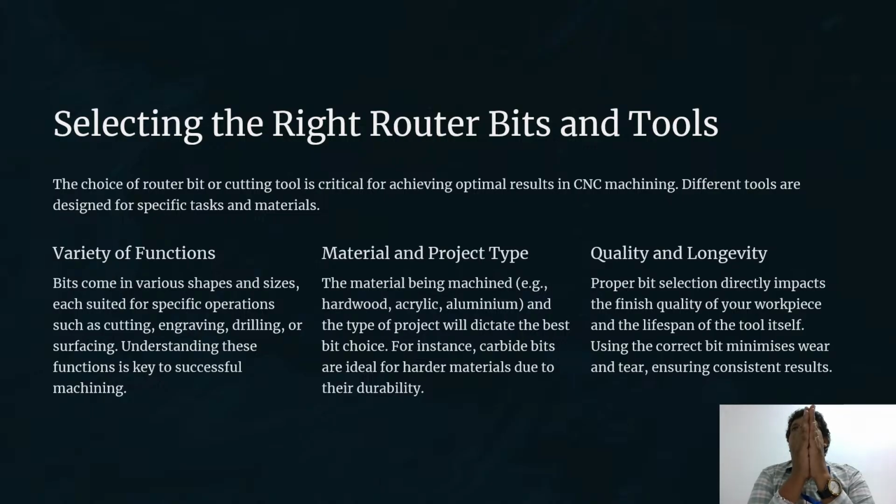When we select a cutter, we have to use the right tool for the right material. For example, when we machine aluminium and we have to use a 3mm end mill, there we will be using a carbide 3-flute cutter. So there we have to note how many flutes there are. There may be end mills with 2 flutes, 3 flutes, 4 flutes, and even more flutes are available.